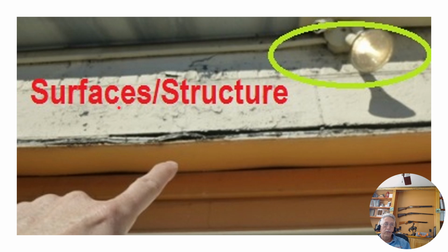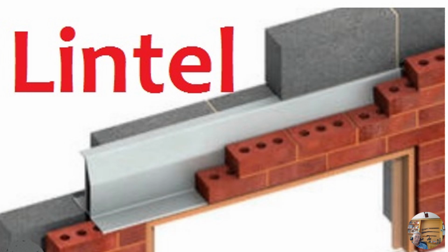If you're not familiar with lintels, I made a little graphic here. All the graphics in this presentation I made with my software. You are welcome to stop the video and do a screen print and download them and use them if you want for your inspection clip art. This lintel, you can see this one's T-shaped on the bottom, and it carries the load. It goes over the window opening, and it carries the load of the brick across there. And this is the part that you have trouble with. It rusts out, and it sometimes warps like we just saw.